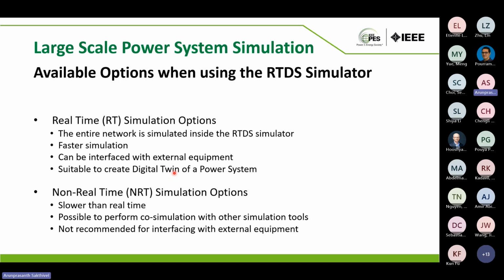And coming down to the non-real-time simulation option, it's often slower than real-time because we are talking about large-scale system modeling. And it's possible to perform co-simulation with other simulation tools to be able to model a very large network. But it's not recommended for interfacing with external equipment.